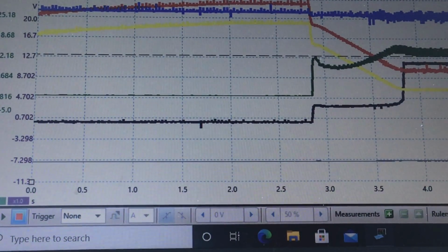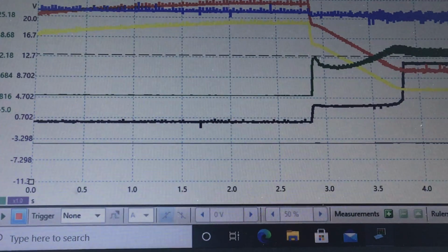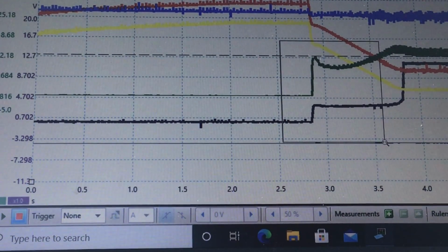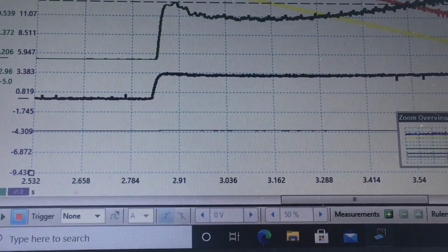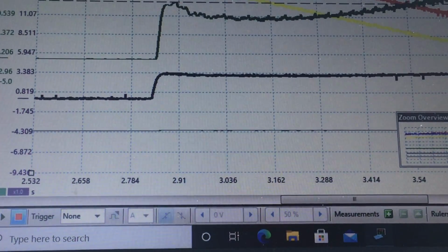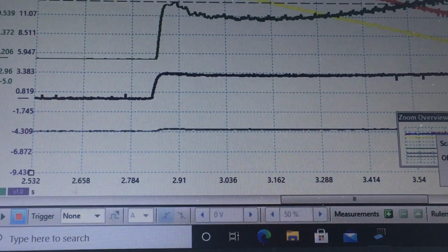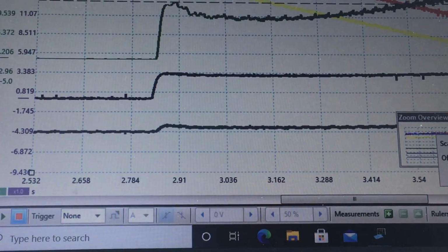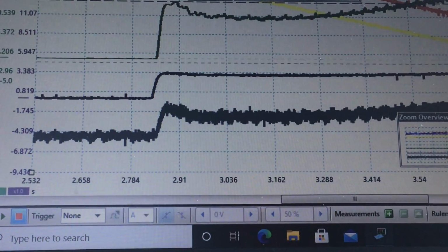And of course, look at our gray channel. That's the voltage drop of the power transistor. I'm going to do some stretch because I'm on a 20 volt scale. We're going to look at voltage drop. I want to stretch the gray guy to see that current flow has an effect on voltage drop. So let's do this, and we'll see that. Okay, I stretched the gray guy. Obviously, that's our voltage drop. Wow. Okay, that definitely was what we expect with more current flowing.